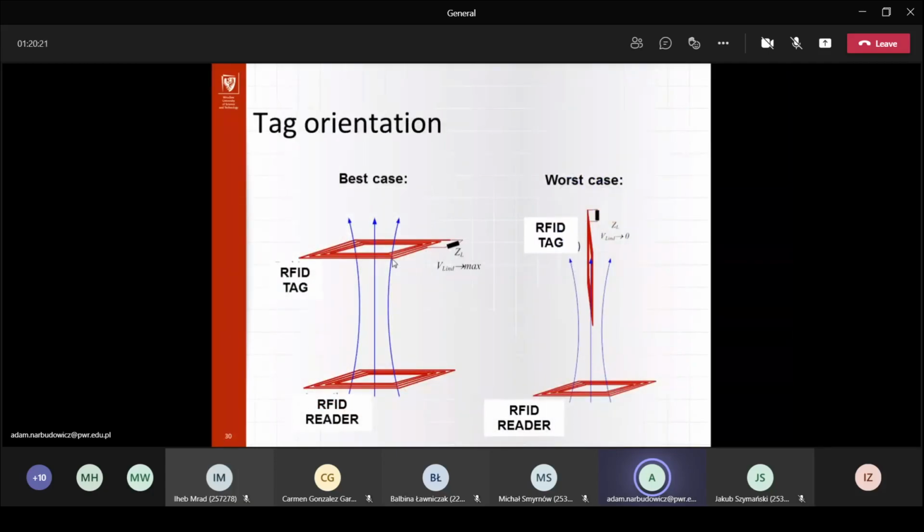Okay, sorry, one more thing I should say here. We go back to the modulation aspects later on. What's also important, from the basic electromagnetic course really, is that this acts as a coil and it requires induction of current into the secondary coil. And of course, the amount of energy induced is proportional to the effective area of the coil within the changing electromagnetic field, right?